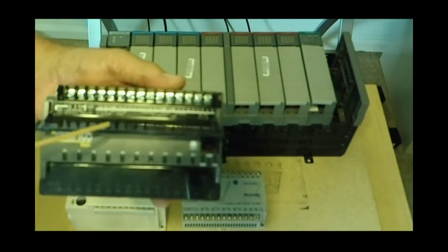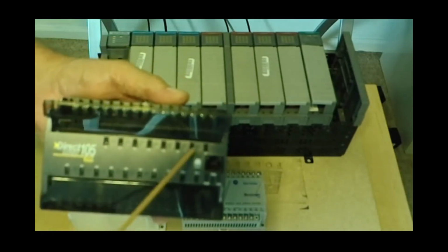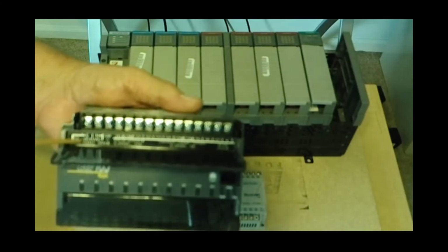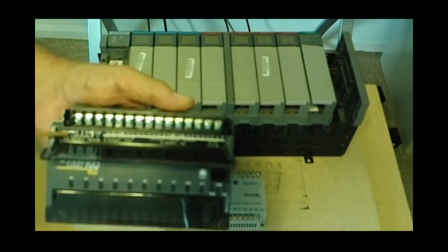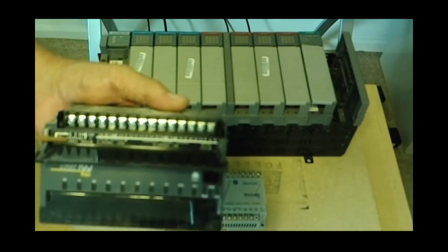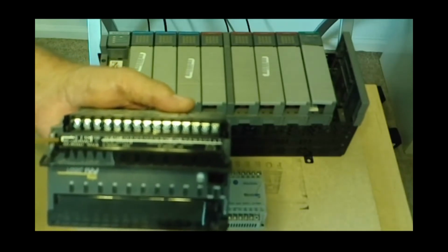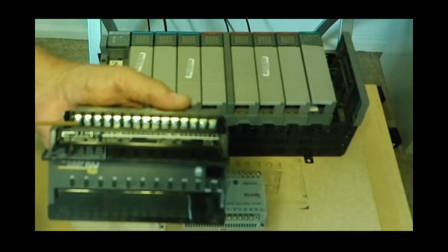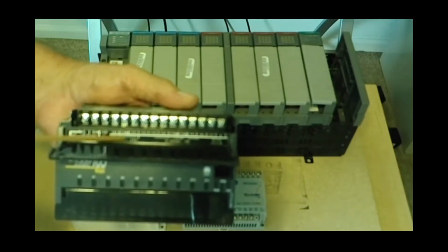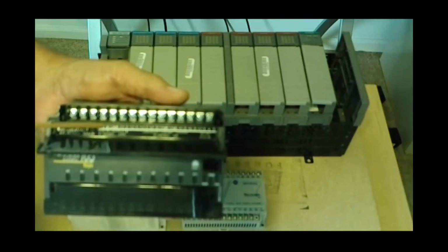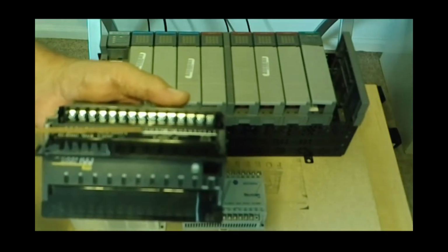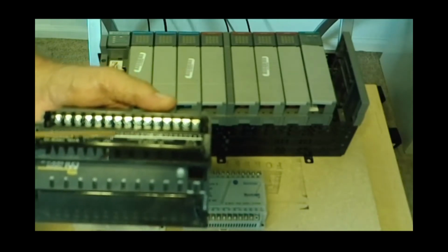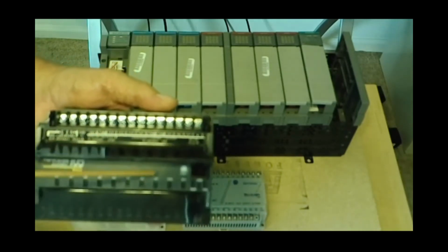So Automation Direct, and again, those lights correspond to the individual screw terminals being used. This one right here brings power in. You bring the power going in right there. It's 85 to 260 volts AC on these terminals with a ground. You have what's called a pulse output, so this will actually send pulses. You have a standard output right there with a common and 3 terminals, common and 3 more terminals.